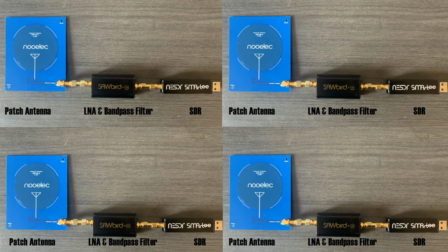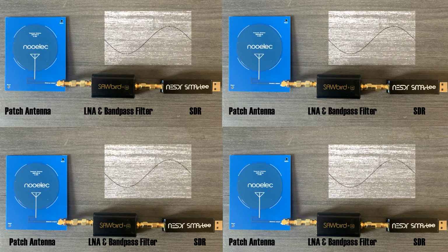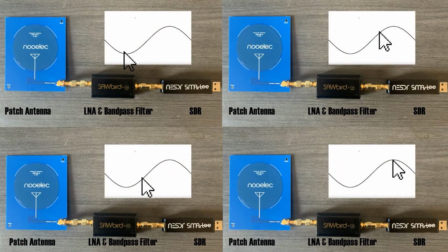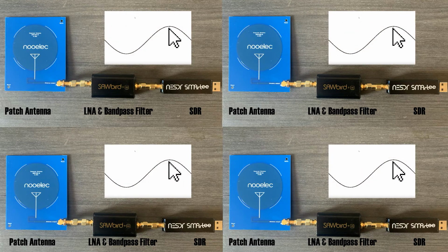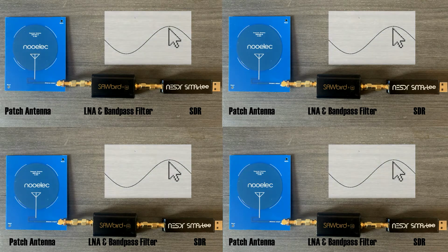Our antenna array uses 4 antennas in a 2x2 square matrix, each separated by a half wavelength. All of the antennas will receive the satellite at slightly different phases. By using our beamforming algorithm, we can align these phases to receive from the direction of the satellite, achieving better signal quality.